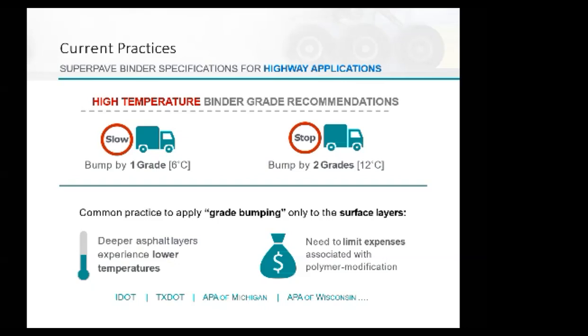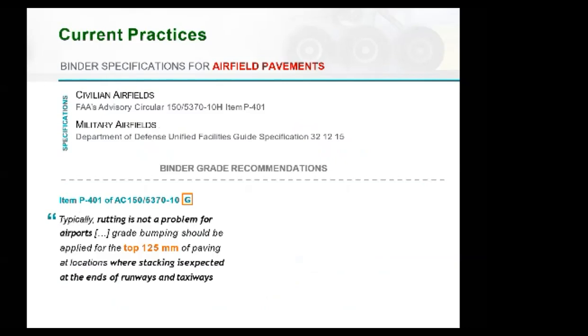So you want to save at the end of the day as much as possible, of course, when you go to the bottom layers. And so it is common practice to apply grade bumping just to the surface layers. A lot of DOTs, a lot of highway agencies actually stipulate that. That's only the surface layers that are subjected to grade bumping.